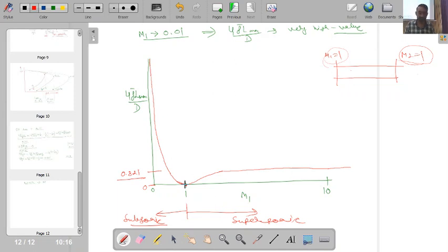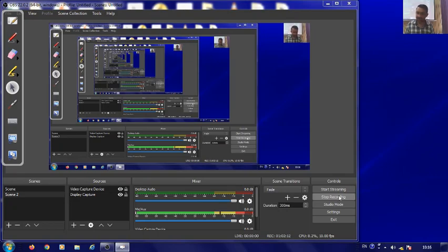Okay, so now I will stop at this point. There are some more points left, a little bit about the Fanno flow. The way earlier I have plotted shock wave over the Rayleigh curve, similarly, I can transform this Fanno curve from the temperature delta S axis to basically a Mollier diagram, because that is nothing but a scaling factor that will only multiply. And then on the same curve, we will try to see the representation of Rayleigh line, Fanno curve, and the normal shock wave, for the given flow conditions. That we will take up in the next lecture, and then we will start our discussion on oblique shock waves.